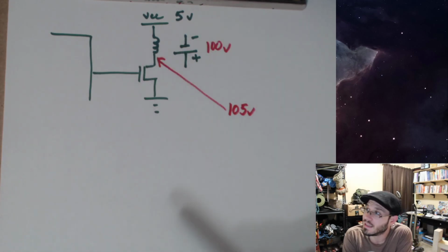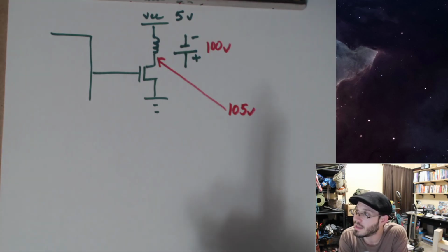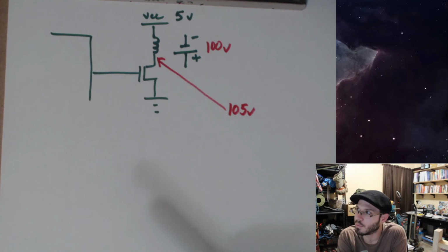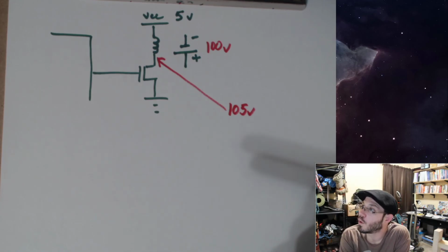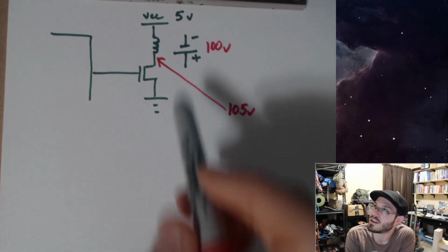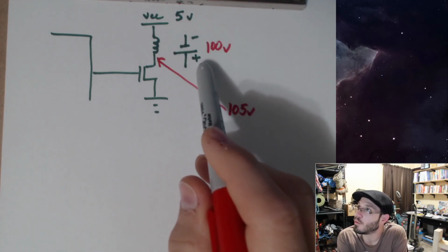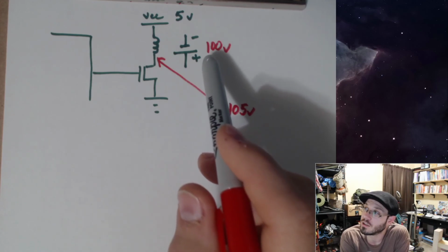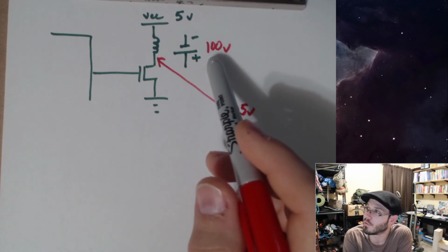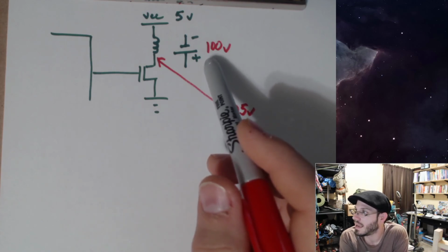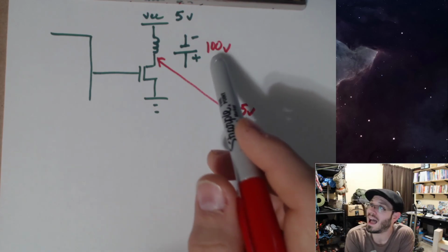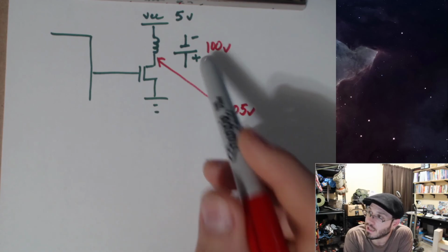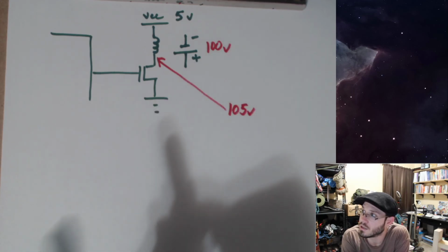Now, to give you a heads up, modern day power supplies, they call them switching power supplies because they are switching an inductor on and off. So for a power supply application, this actually is desirable because it lets me create voltages that are much larger than my input voltages, because there's no limit to how high this voltage is of a collapsing magnetic field of this inductor.